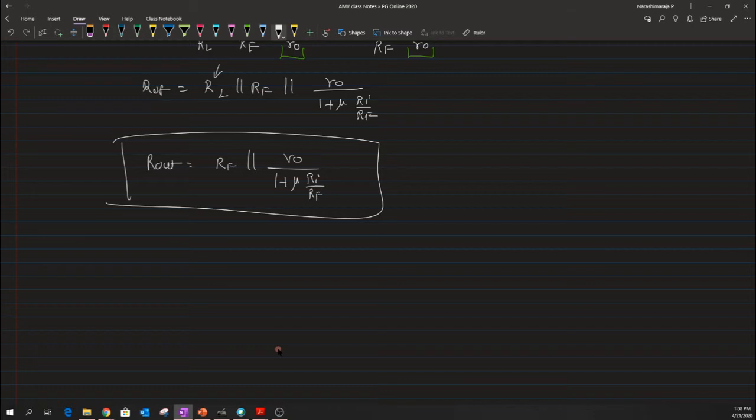Okay. Now for the case for numerical values that are given, the value of input impedance of the basic amplifier Ri can be written as, again I'm rewriting this RF and RS, and we know that this RID is taken as infinity, and that goes in parallel with 10k, and RS is having an impedance value of 1k, and all of these combinations will end up having a value of 0.91 kilo ohms.